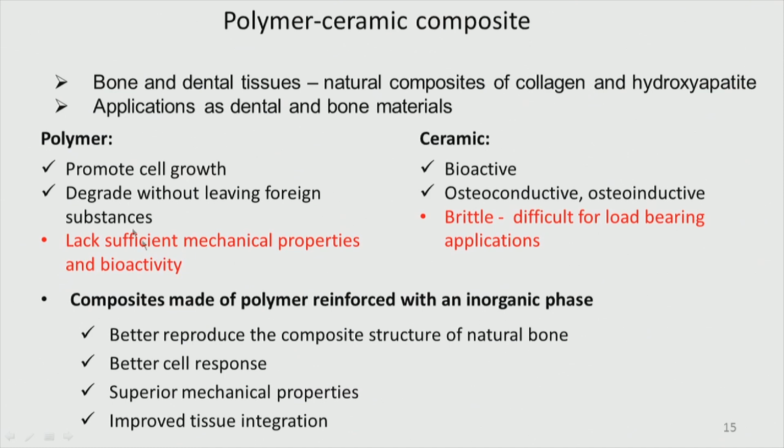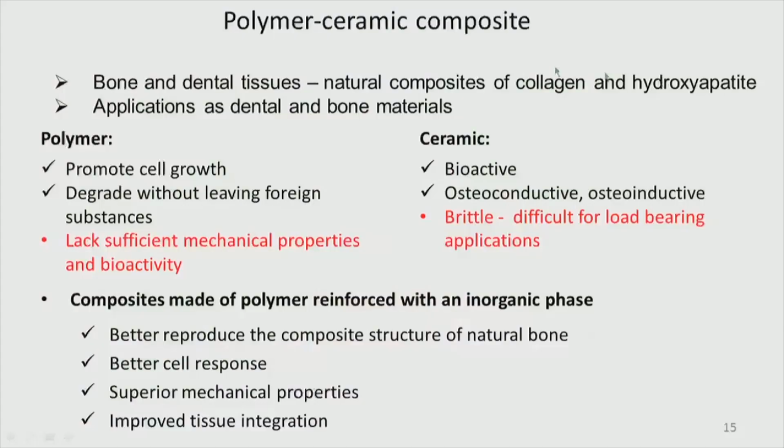Of course, polymers do not have good mechanical properties, and they are also not bioactive, that is taken care of by these ceramics. Ceramics are brittle, so they cannot take over load bearing applications, whereas polymers are much better than these ceramics. So, this is a very good example of a polymer ceramic composite, and a lot of dental bone applications have this type of combination.